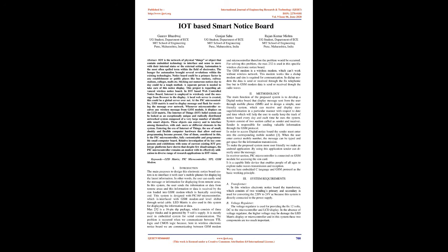A problem occurs when we communicate between TTL logic and CMOS logic because, here in the wireless electronic notice board, we are communicating between the GSM modem and the microcontroller. For solving this problem, the MAX232 is used in this specific wireless electronic notice board.